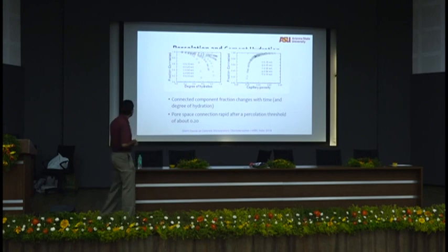Now, very important, look at this. What is this curve? What water cement ratio is that curve? 0.35. See that at a degree of hydration of about 0.6, I have zero connectivity between water, right? Doesn't have to be exact, roughly at a hydration of 0.55, roughly 0.58.